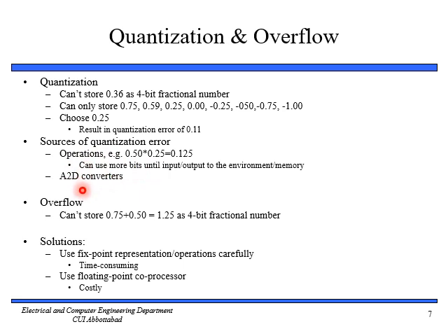One other source of quantization is the analog to digital converter. When we are converting analog data to digital data, we have a number of levels. Like if we have a voltage level of 4.325 or 4.6, we are going to chop it to, let's say, 4.5 or 4. So there is a quantization error in the sampling process, because first we sample and then we quantize. Analog to digital conversion involves two steps. Number one, sampling, that is chopping off the signal along the x-axis, and then quantization, which means chopping off the signal along the y-axis.